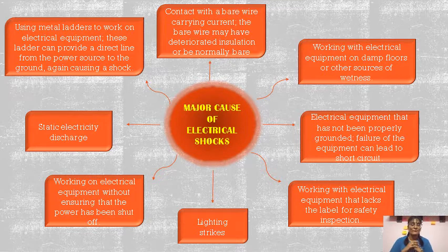There are various causes of electric shocks, and one of them may be our carelessness, but there are some other reasons also that cause electrical shock. First, contact with a bare wire carrying current. The bare wire may have deteriorated insulation or be normally bad. Second, working with electrical equipment on damp floors or other sorts of wetness. Wetness will be the main reason causing electrical shock.